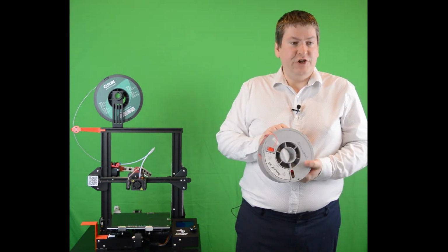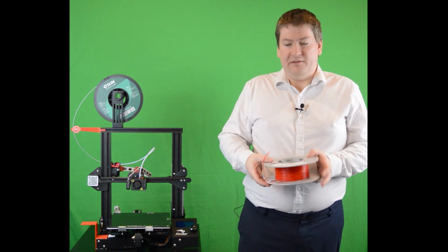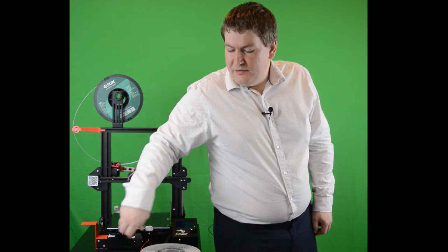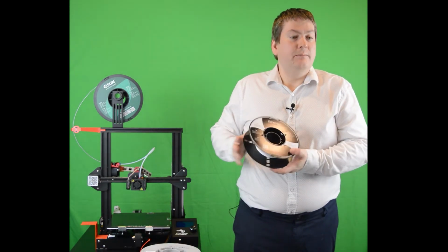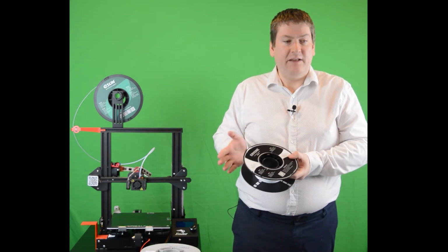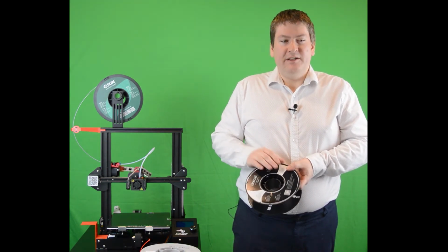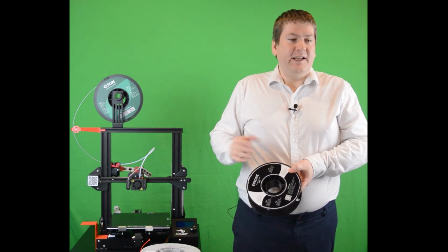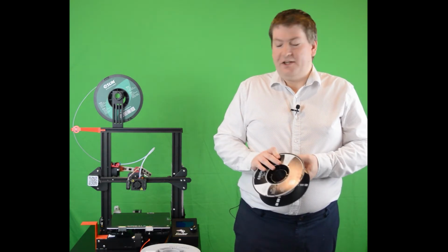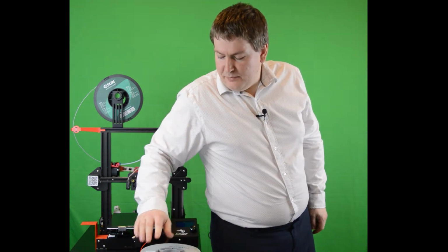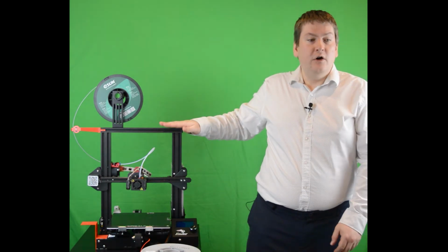This one is PETG. It's sort of in the middle between hard to use and good results of print. But the most commonly used one is something called PLA. This is a real easy plastic to print. Gets great looking prints, especially fine detail, but they tend to be a little bit weaker and they're not that heat resistant. They could melt in your car, for example. But both PLA and PETG have the advantage of you can print them on a home printer like this without many modifications.